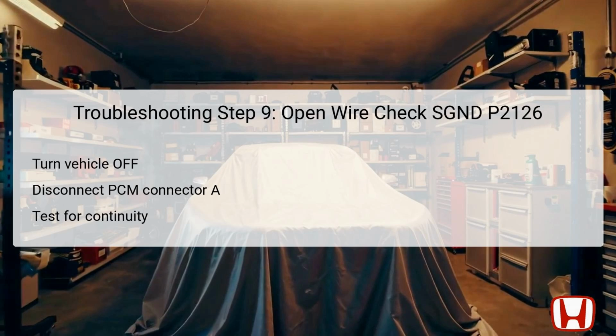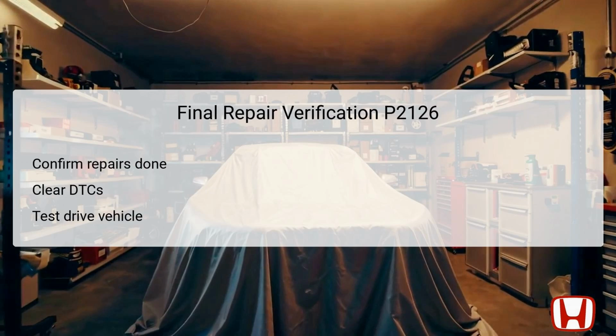If you are able to confirm continuity, you can once again consider that line free from fault. Should there be a lack of continuity, repairs on the SGND wire are essential to ensure accurate electrical performance. After successfully completing the previous troubleshooting steps, it's crucial to verify that all necessary repairs have been completed effectively. Start by confirming any parts have been correctly installed, especially after replacing components like the APP sensor or PCM.